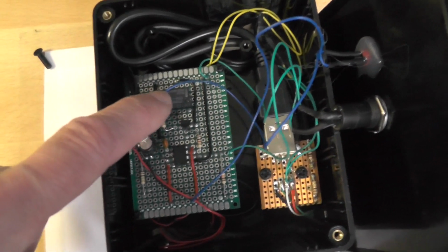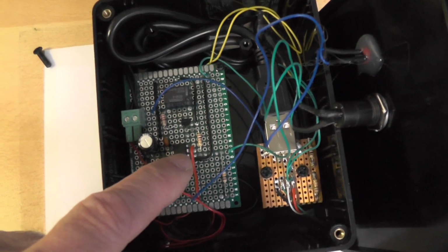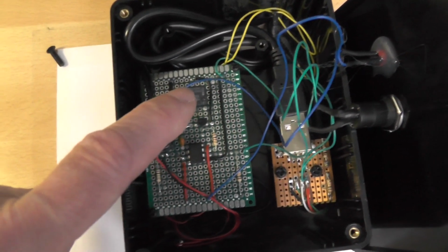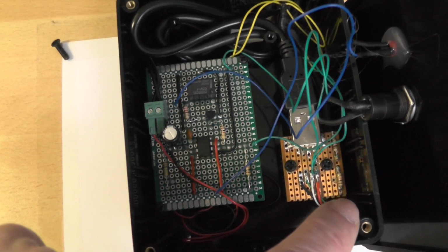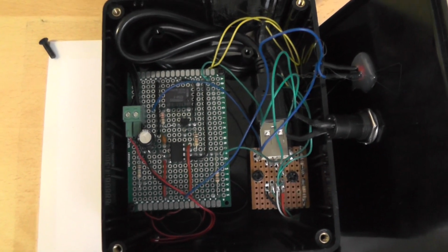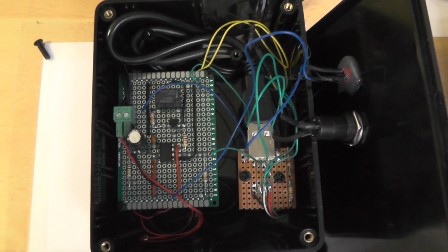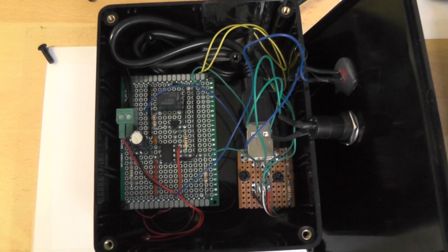And this relay is activated by the timer. So when the button is pressed on the box, the IC555 timer activates that relay for 2 minutes, which closes that connection and therefore turns on the barcode scanner. Simple as that. I'll put a circuit diagram up immediately after this video, and the Python coding and this circuit diagram will all be available on GitHub.